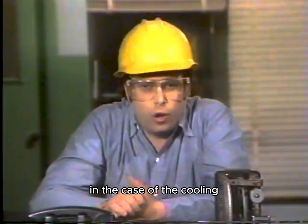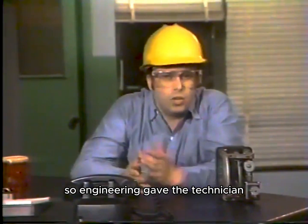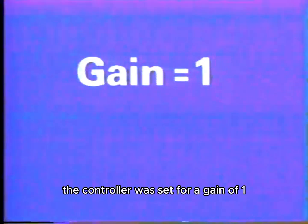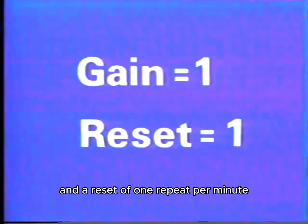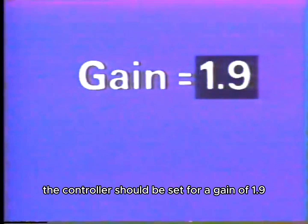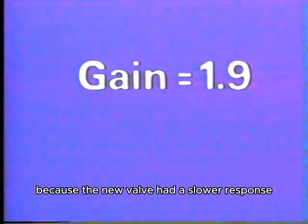In the case of the cooling water temperature control system, the control valve was replaced with a different valve. The new control valve was expected to respond more slowly than the old one, so engineering gave the technician new controller settings to use. As you recall, with the old valve, the controller was set for a gain of 1 and a reset of 1 repeat per minute.